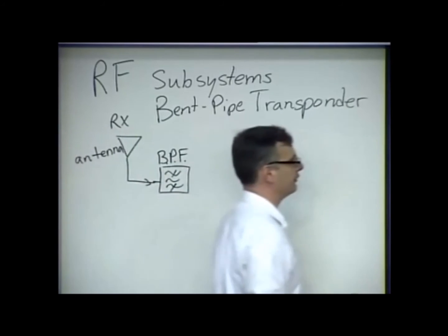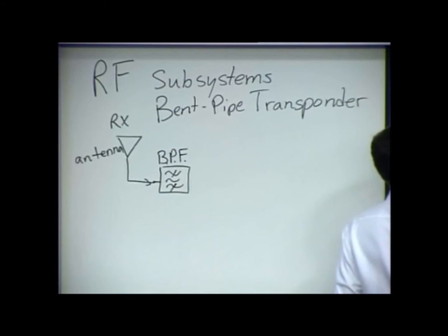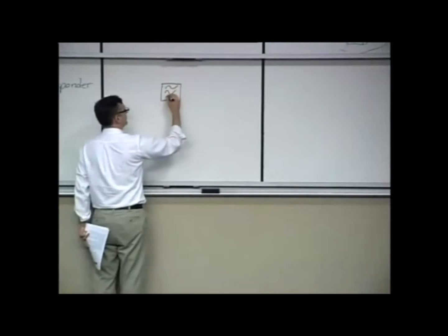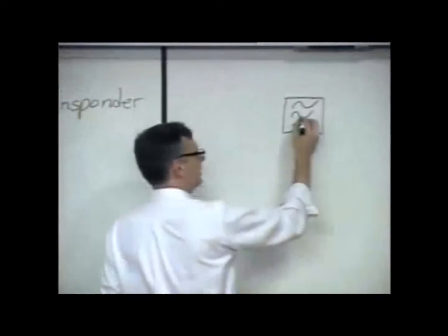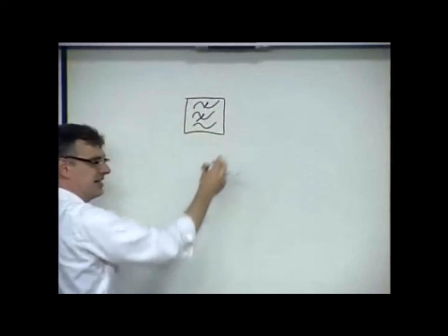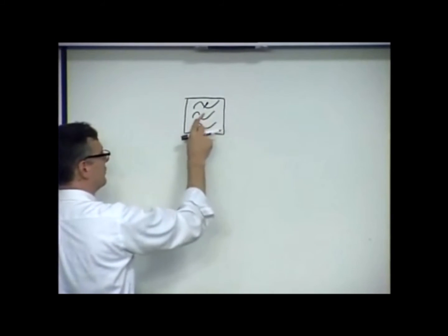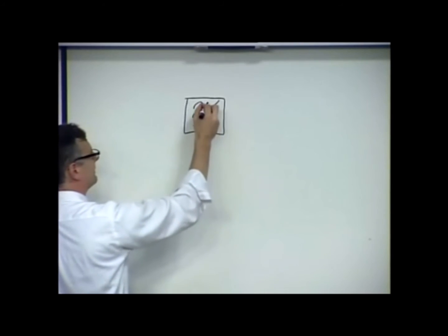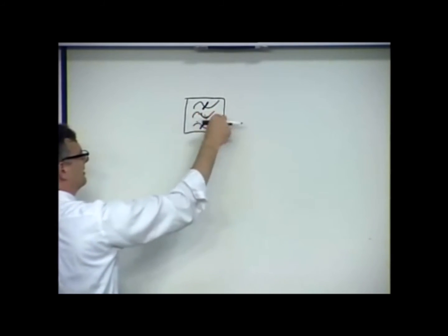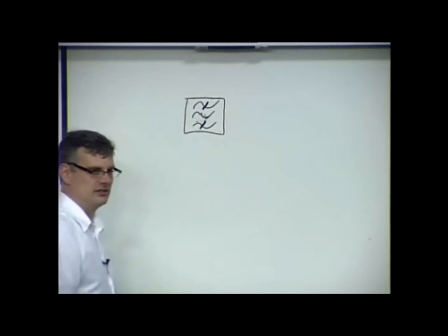And, of course, I draw filters. We'll have low-pass filters, high-pass filters, notch filters. It's pretty standard terminology in block diagramming communication systems. This is a low-pass filter. It blocks the high and the medium frequencies. I drew a bandpass filter that has the high and the low blocked out. It lets this one through.